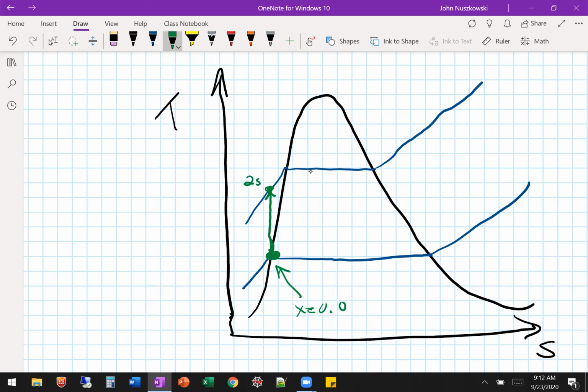If we're isentropic. Well, we have isentropic efficiency. So just like last class, we did that for the turbine, we have one now for the pump. So that would take us a little bit to the right on the same pressure line. And that would take us to 2 actual right there, because same inlet and outlet pressure, but we have a little bit of irreversibility, so our entropy increases.